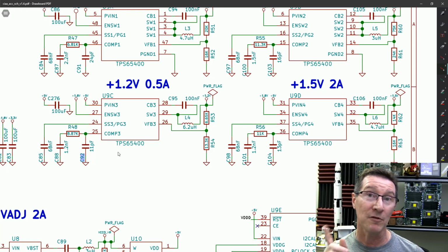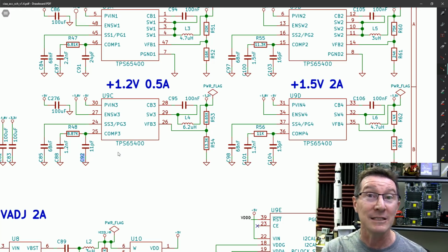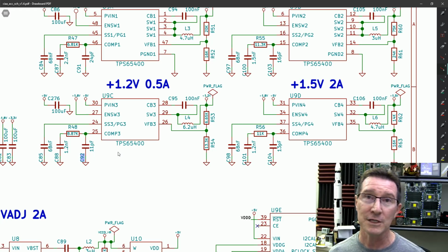And a good bill of materials will also have a substitute, like different brands. In fact, it was company policy at some companies that I've worked at, especially military type ones, where you'd have 3 different manufacturer part number variants. So you'd have 3 choices so that the purchasing people can choose any one of those, and it doesn't matter, that part was fully qualified for use in the design.